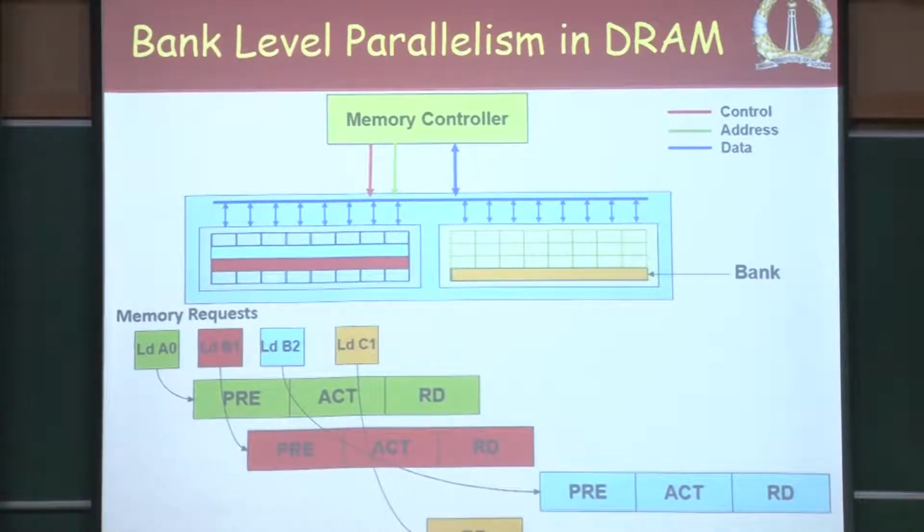If you have multiple banks, there are multiple banks in a device, and if you have multiple ranks, you will have more banks, you can now start doing these activities in parallel and try to get some level of parallelism. Already there are multiple banks and for each bank there is one row buffer. Your question is why can't we have more row buffers per bank? That is an engineering question, you can think about it and we can see what benefits one would get from that.